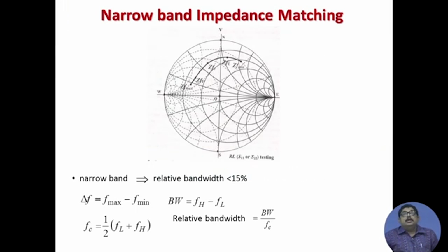Now, basically we will see that if you are designing an LC based impedance matching network, L and C are frequency dependent, actually they have reactances which are frequency dependent. So we can say the impedance of the matching network is frequency dependent, and the match is achieved at a particular frequency. Now, any signal, our baseband signals, is composed of various frequency signals.